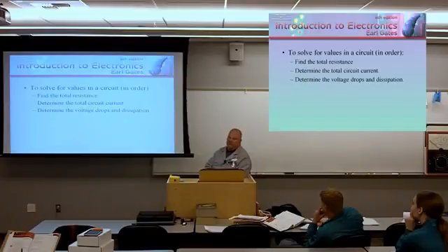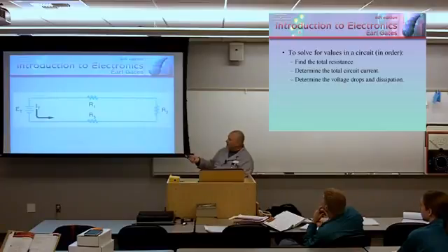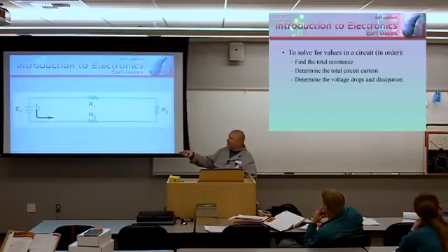And the thing of it is, when you get out into industry or in lab, I may give you this, but this is encased in epoxy. You can't even get to it. You can't even get a part number off of it. You can't even take a reading of it. So you're going to have to use these laws and say, well, I remember Joe said that this is equal to this plus this plus this. I know what this is, I know what this is, I know what this is, but I don't know what this is. So then you can say the remainder is equal to this.